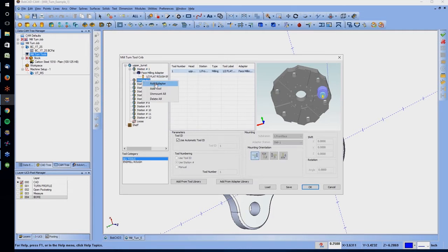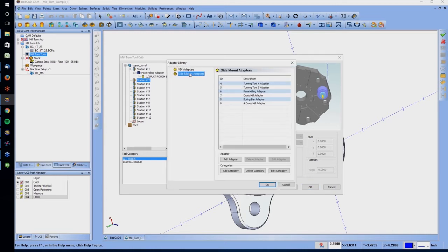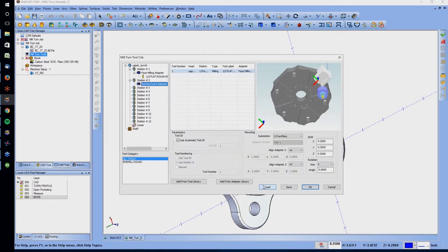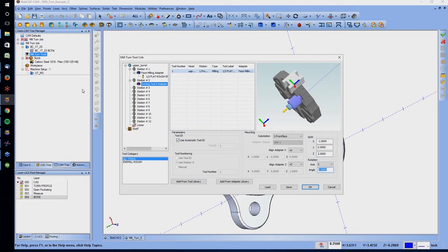They'll just be lathe settings, so just so you guys can see, let's add an adapter for a lathe. Alright, there's that one. Okay. We can reposition it, so let's move it up next 1 inch. No, let's go negative. And then let's move over Z. Okay. And then you can attach your lathe tools to it.